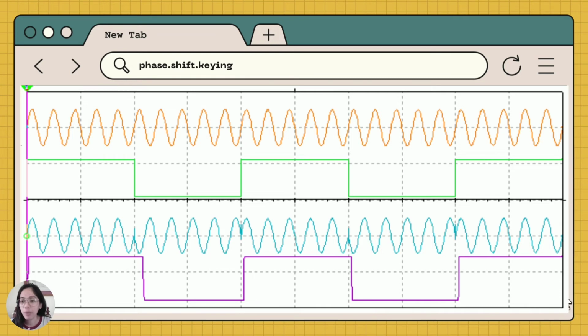In these waveforms, the modulating signal is a binary sequence of 1 and 0, while as you can see on the modulated signal, which is the PSK, there are phase shifts of 180 degrees as the binary sequence changes from 1 to 0 and from 0 to 1. Lastly, the demodulated signal is well retrieved by the circuit.